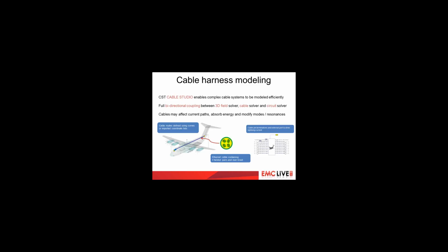This truly integrated approach ensures that the cable becomes part of the overall structure, and it therefore affects the current paths. It also absorbs energy and modifies any modes and resonances inside the aircraft. Cable pins may be terminated in the circuit simulation tool Design Studio, from which the entire field, cable, circuit, transient co-simulation may be controlled.